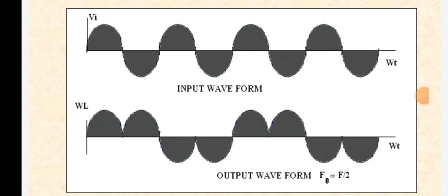The negative group allows all negative half waves coming to it and also converts positive half waves into negative half waves. The firing pulses are given in such a way that half waves 3, 4, 7 and 8 pass through it. It allows negative half waves 4 and 8 and also converts positive half waves 3 and 7 into negative ones, and they are shown in this figure.